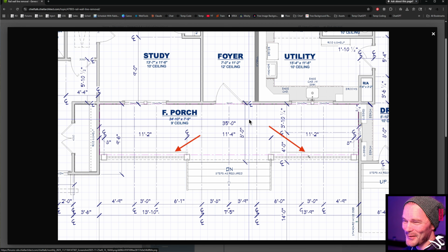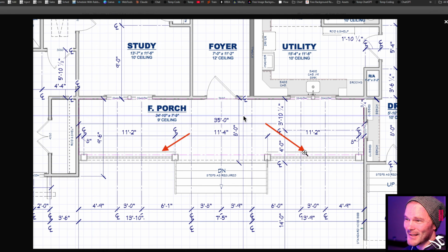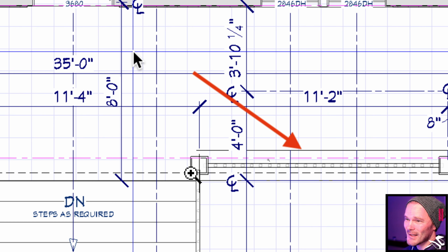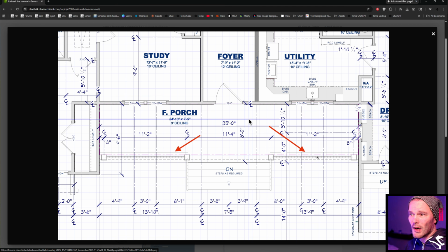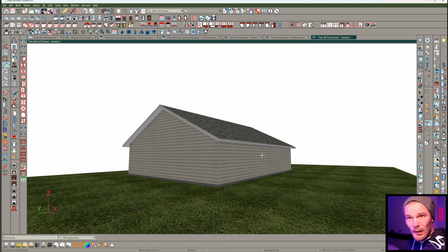It's the first thing I do when I get someone else's plan. That's an old school thing, I guess. Anyways, see this extra line here? That's happening because that is the full thickness of the railing. Two things here. There's no reason not to set the railing thickness back to the thickness of your actual newel posts or your rails, etc. That might be what I would do, unless for some reason you wanted the wall to drive the thickness of the railing.